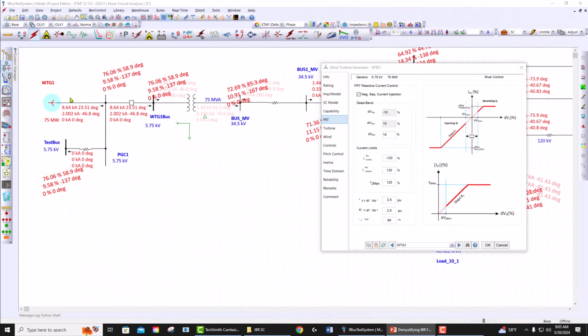So this is what's happening here. It means that during the iterations, probably the voltage has gone up above the 10% in case of the negative sequence, and that's why the curve has become continuous. Even though the negative sequence voltage has gone down below 10%, we still continue injecting negative sequence. That's what typically happens in the time domain as well, because of the timers and the controller scheme to avoid toggling. So keep in mind that what you see sometimes may not match, but there are some details involved in how we implement the short circuit current calculations.